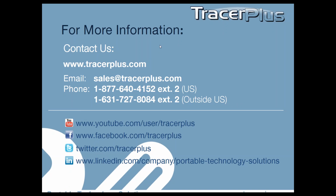We do have some questions here. Questions on if you can use a mobile RFID reader as a tag locator with both a passive and active tag. I'm not sure how that would work for an active tag, being that it's sort of a beacon. I think an active tag you would probably just be able to locate and know where it is, whereas a passive tag you can use what we call the Geiger counter or tag locator in our Tracer Plus software to try and locate an item.